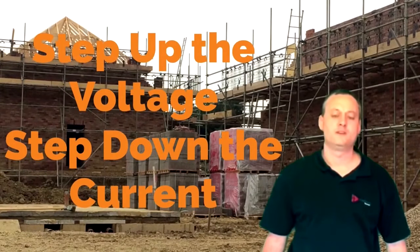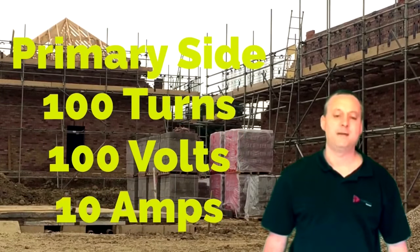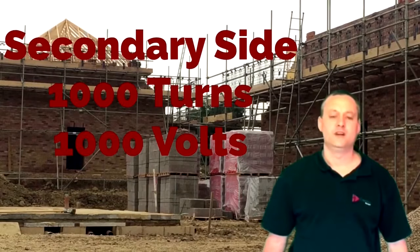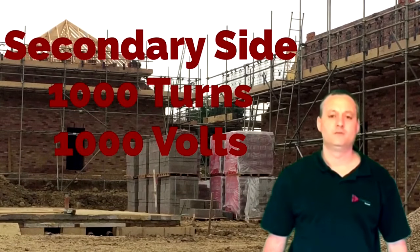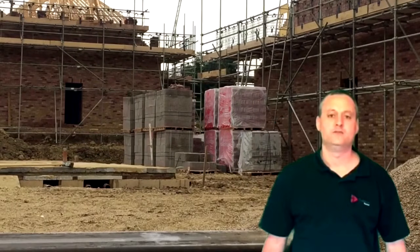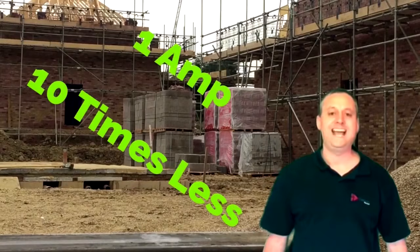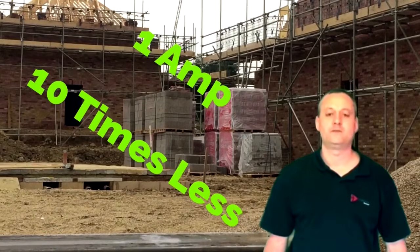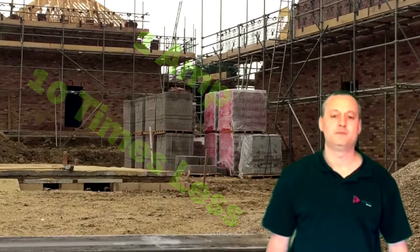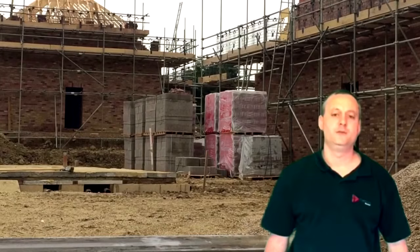So if a primary side has 100 turns and 100 volts and 10 amps, if our secondary side had 1,000 turns, 1,000 volts, it would only have 1 amp on the actual secondary side. So in other words, we've stepped up the voltage by 10 times. So we've gone from 100 to 1,000, but we've actually brought the current down by 10 times from 10 amps down to 1 amp. And we discussed the massive benefits with this, with the distribution systems.